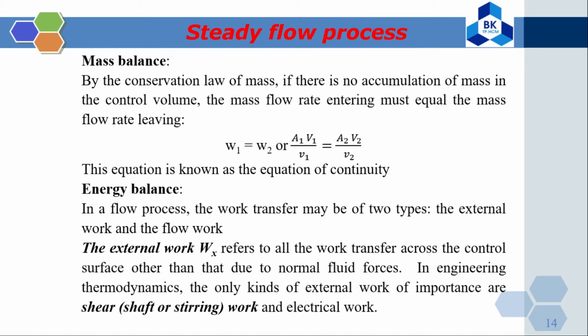For the energy, we also have the energy balance. In the process, the work transfer may be of two types: the external work and the flow work. For external work, Wx refers to all the work transfer across the control surface other than that due to the normal flow forces. In engineering thermodynamics, the only kinds of external work that are important are the shear work, or shaft work, I mean the work turning the shaft of the motor around, and the electrical work.